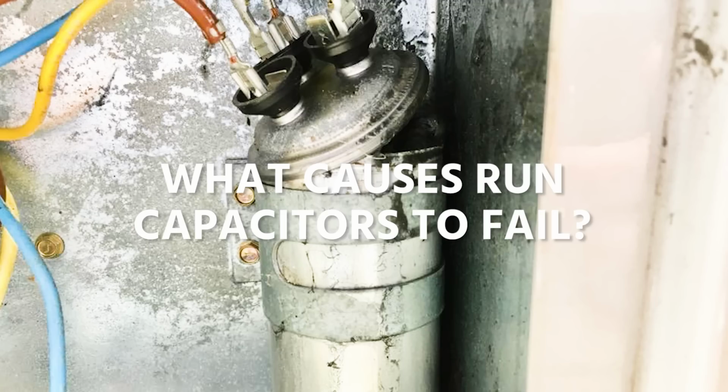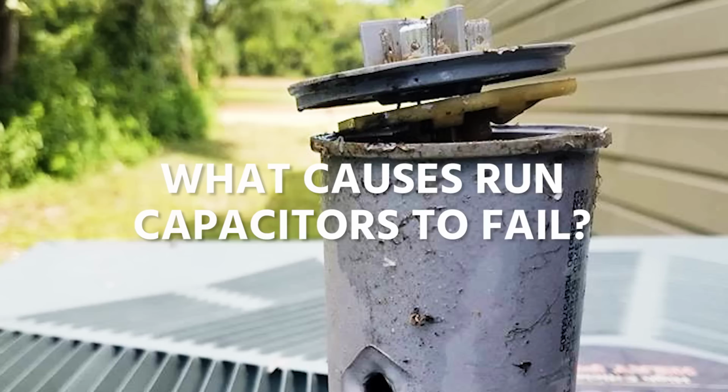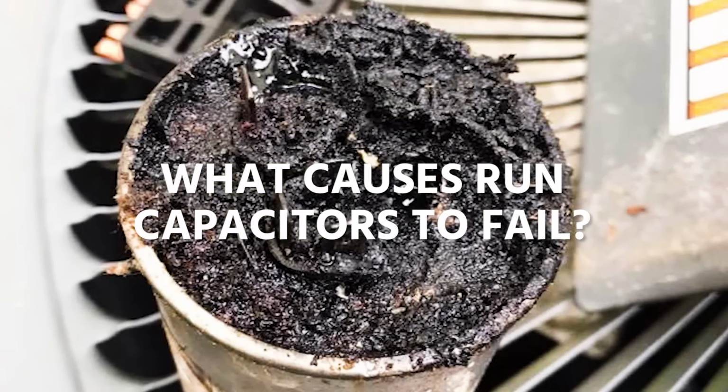And to start with, before we go any further, you have to have a basic understanding of what a capacitor is. The best way that I can get you to imagine it is to think of a run capacitor like a storage tank or a pressure tank. If you're used to pressure tanks in, say, a well pump, you understand that it pressurizes that pressure tank, and the amount of water that can be stored in it is contingent on the incoming pressure. You can't have more pressure in the pressure tank than the incoming pressure. And that's how a capacitor works.